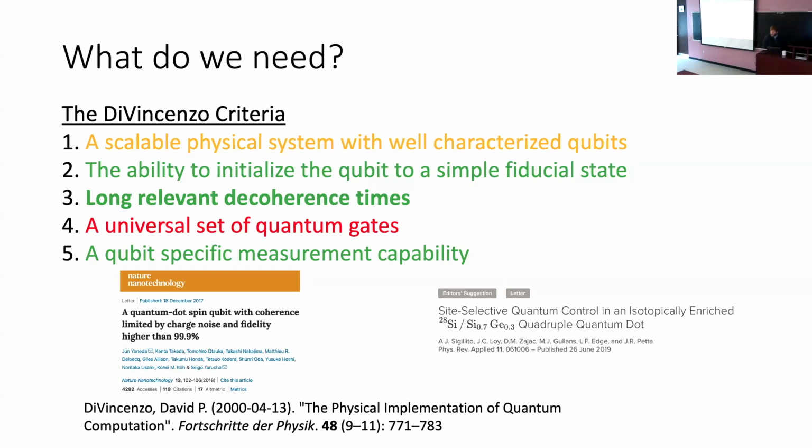Since I think it was '59, George Feher, way back then, knew that coherence times and line widths were limited by nuclear impurities in silicon. And we knew that we just needed to grow the material in order to take advantage of silicon 28. It turns out that silicon has one isotope, silicon 28, that is nuclear spin 0. I'm sorry, it has 2 isotopes, silicon 30 as well, but we enriched to silicon 28 to remove all those impurities.